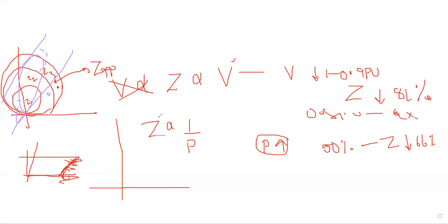Same. See, the philosophy of getting these blinders depends upon the... See, now this is the general idea I derived from the distance protection settings. Now, based on the load encroachments, or maybe due to the power swings, this is the concept of load encroachment. Power swing is maybe a sudden load change, or maybe due to some disturbances.